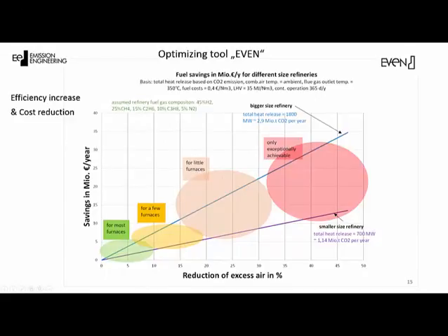We are often asked about the savings derived from excess air reduction. This is why on this slide we have tried to calculate some savings in euros per reduction of excess air. Of course, potential savings depend on the size of the refinery concerning the heat release to all furnaces and the real average oxygen contents in the flue gas. Again, as measurements of oxygen levels are very often non-representative, savings may appear smaller than they actually are.